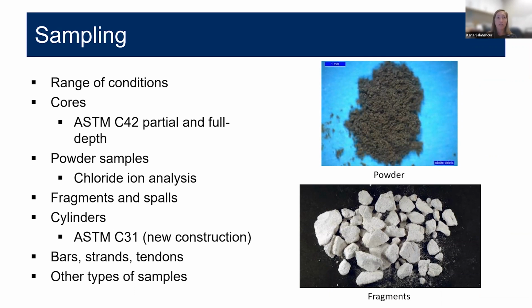Also, if we're specifically investigating a problem, we recommend taking cores representative of each type of distress and also including a control and non-distressed core.